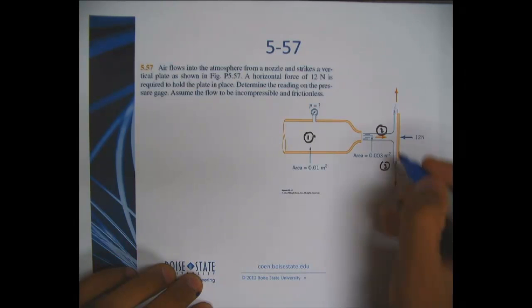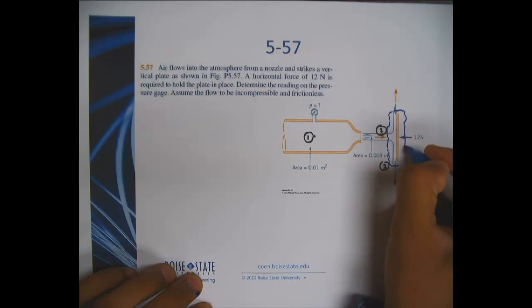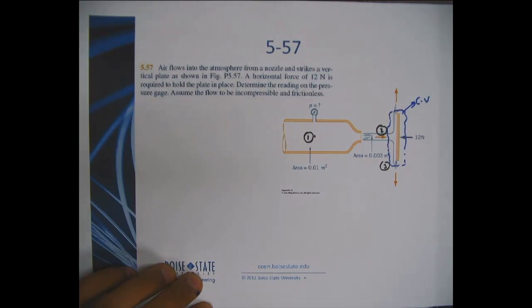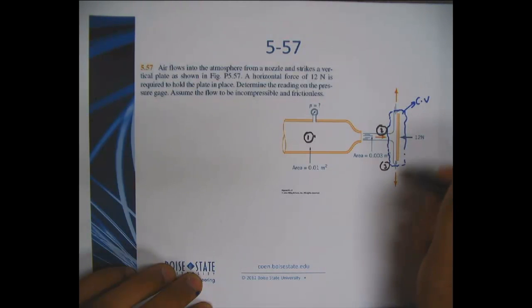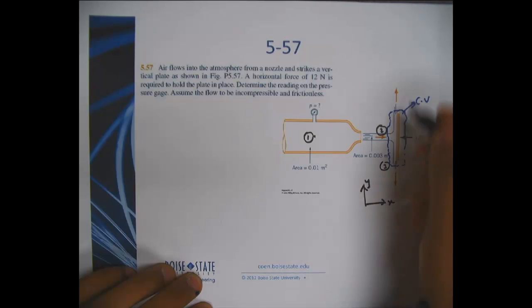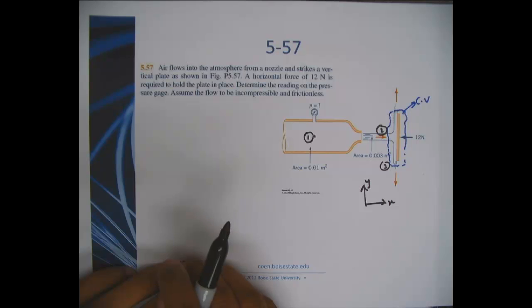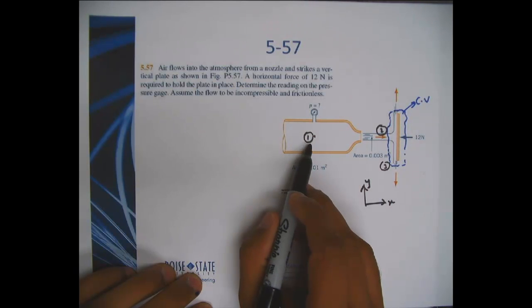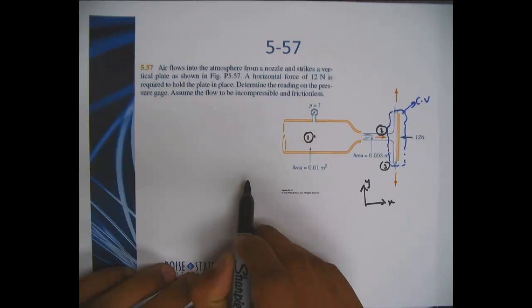Since we have done a problem like this, by now you know that this is the control volume you would pick, okay, for this region, and you know that the momentums in this direction, if you say x and y, cancel out each other since you assume that the flow is symmetric. Okay, first let's try to determine if we can write a relationship for pressure at 1.